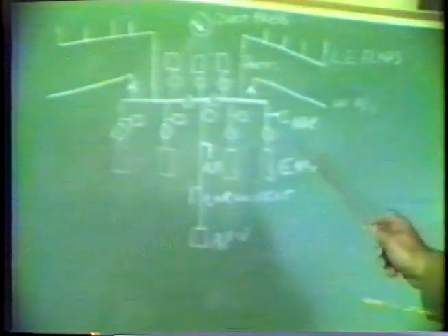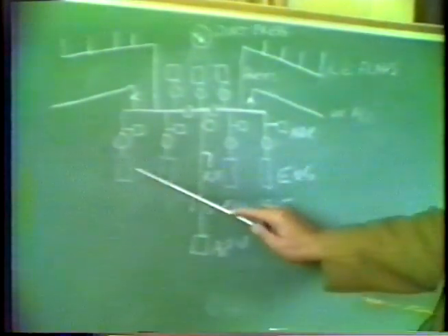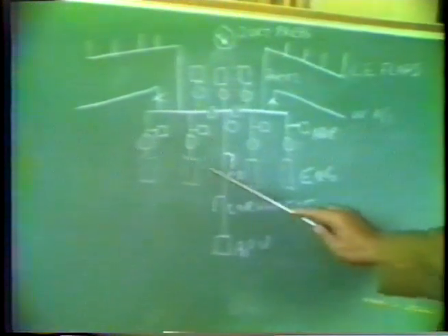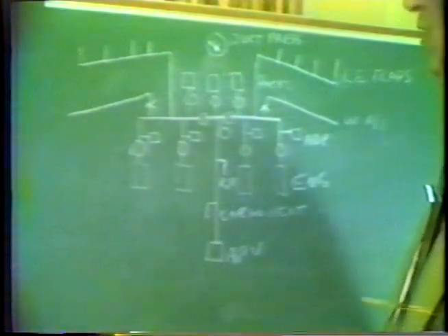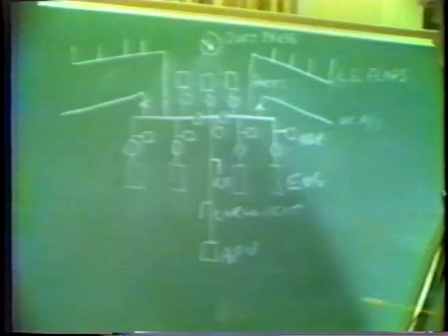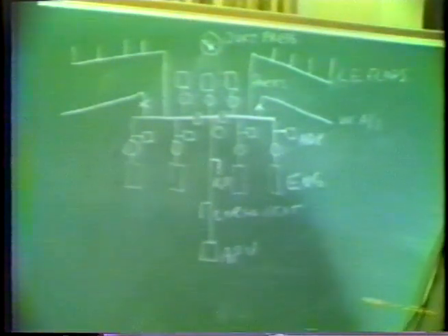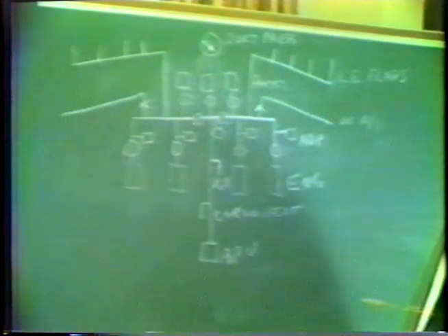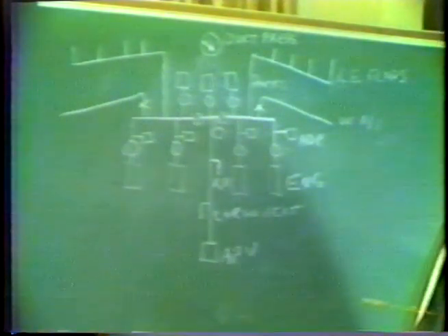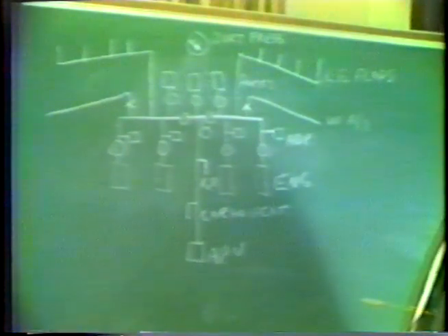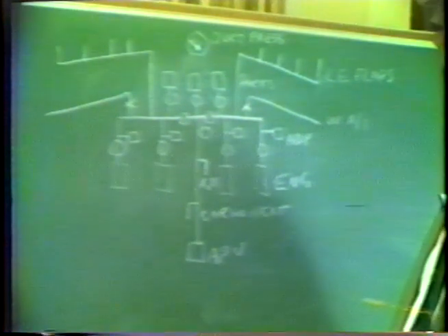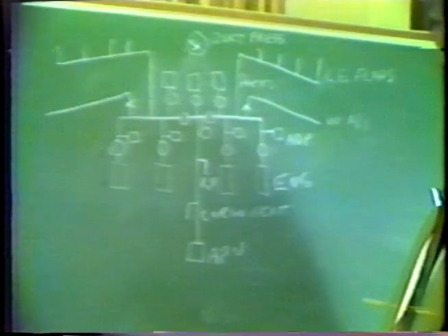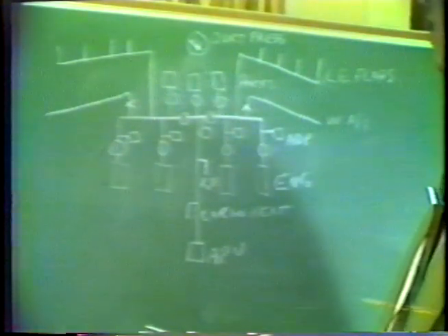Over here I have a little sketch of the entire pneumatic system. And starting with the basic source of air, we have the 4 engine bleeds. The air coming out of the engine comes from 2 different sources, high stage and low stage air. The low stage air is used most of the time. However, under low engine thrust, the low stage air does not provide enough air to maintain pressurization in the aircraft, so an automatic device switches in high stage air.